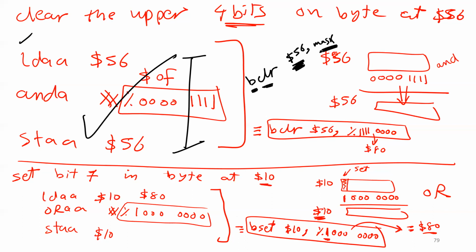The way you do this mask is similar to the mask you did before. So I'm going to put 1 1 1 1, then 0 0 0 0. Why 1 1 1 1? Because this is similar to branch if clear, branch if set, which I explained before. When you put 1, you are telling the instruction, I'm interested in this bit, so please clear it. All the time, the bits you are interested in, just put 1, and this instruction is going to clear them.